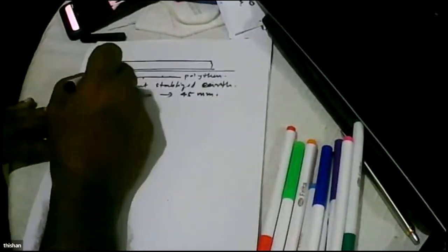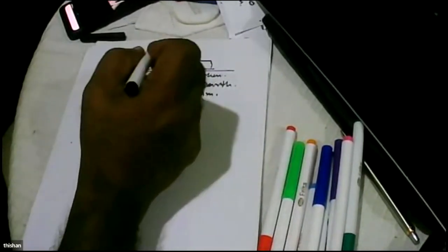And then we can lay a thin concrete, or even a rich mortar mix would do. Because what you want is a temporary surface large enough to cast these slabs. But we want it to be perfectly level. Otherwise, our slabs may not have a perfectly level soffit.